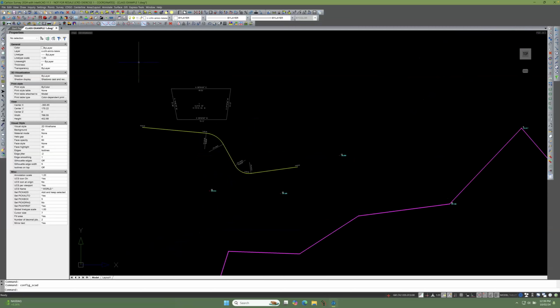And there's all kinds of other things. You could have a series of points. Let's say you go out in the field and you're surveying and you get a bunch of points that you surveyed, a bunch of centerline shots along a roadway. You can go to that center line and do a best fit.